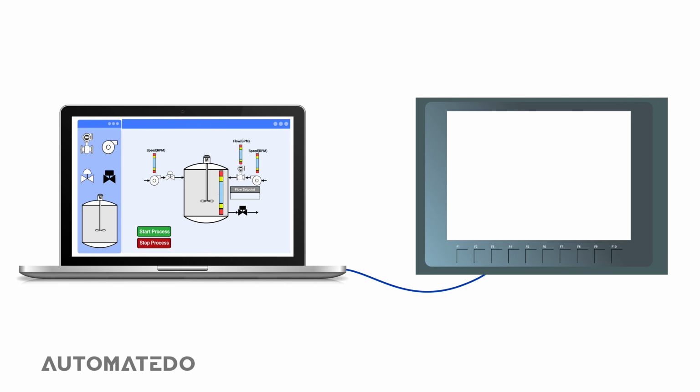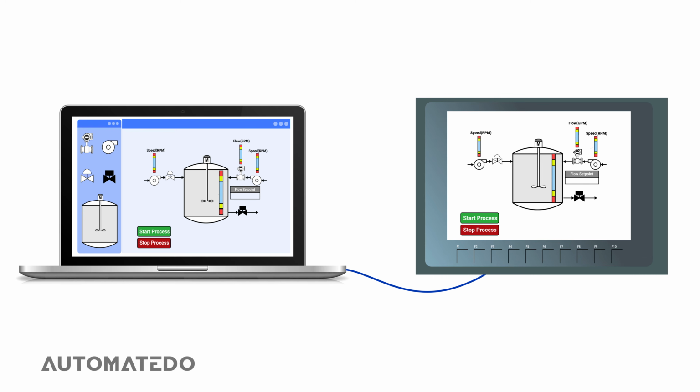The second step that applies in the HMI software configuration is runtime. The design dashboard is downloaded to the HMI from the personal computer, and then the HMI runs the program on its screen to be visible to operators for further use.